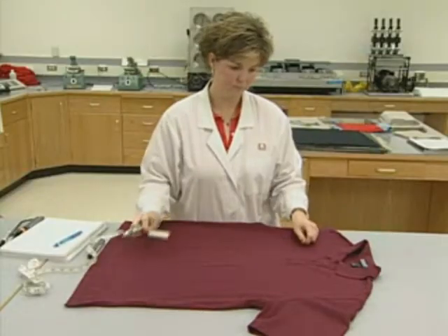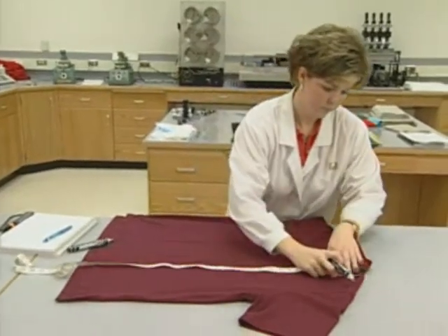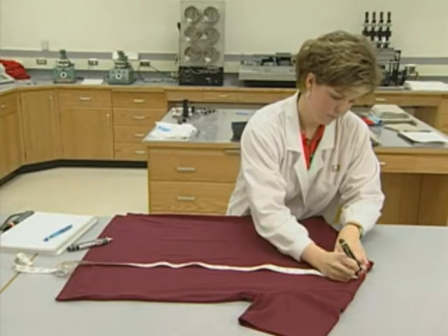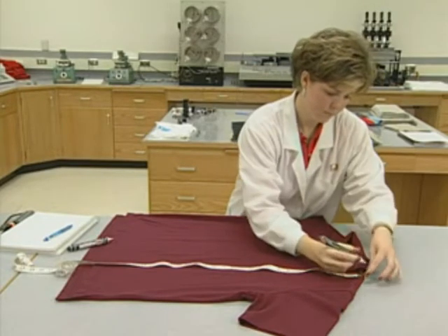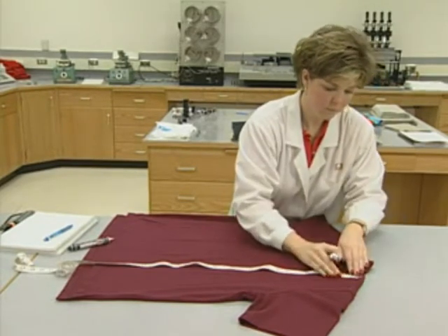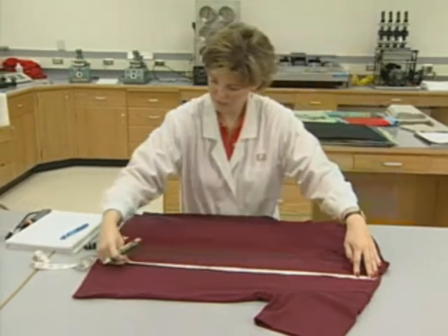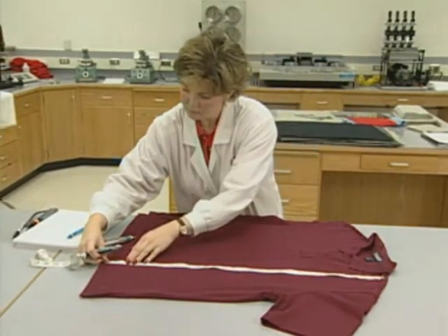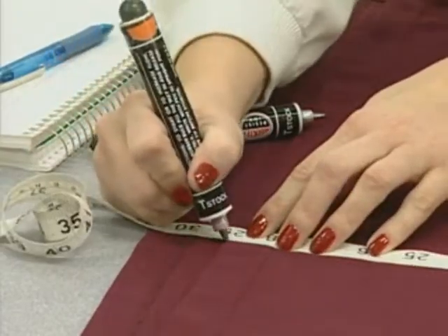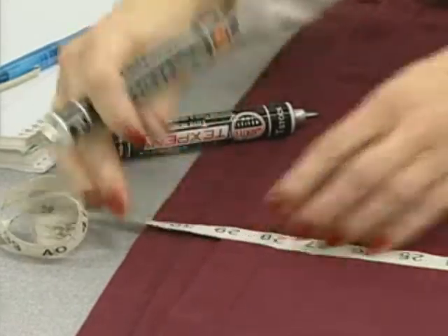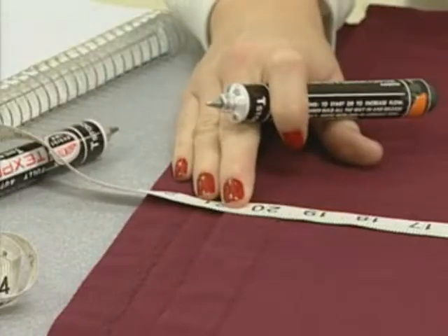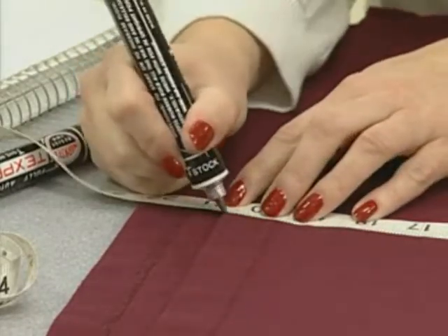The benchmark for length shrinkage is determined by measuring from where the collar is sewn into the shirt at the junction of the shoulder seam. A mark is made at this point, and a tape measure is stretched from this point directly down to the bottom edge of the waist hem. A mark is made at this point, and the length is recorded to the 1/10 of an inch. Multiple and alternate positions may also be marked for the front and the back.